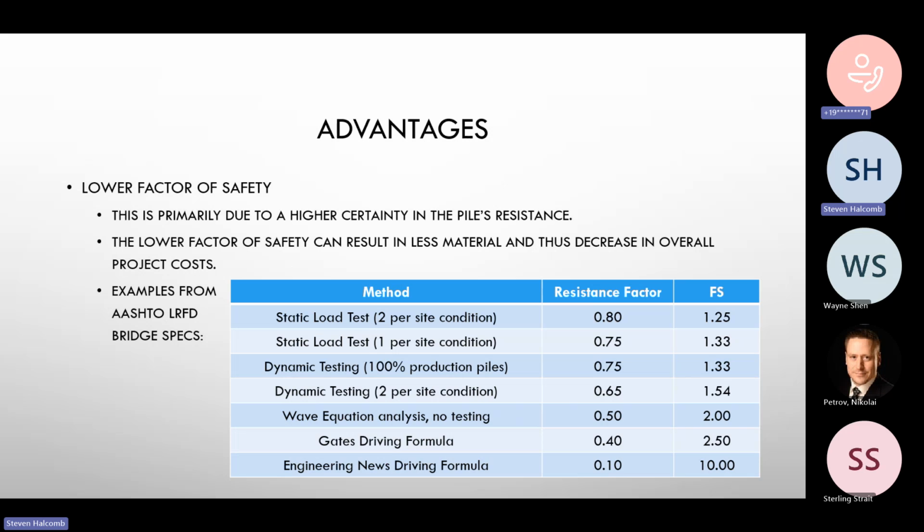So one of the biggest disadvantages is a lower factor of safety. And I really liked what Dave provided from the AASHTO perspective. It gives a bit more comprehension. The IBC doesn't give as much. It talks about it relative to your design stresses, that's the reference in 1810, but it doesn't give you a whole lot more guidance. AASHTO gives you a little bit better. It says, how can I lower my factor of safety based on what I'm willing to do? Because this is a construction verification technique, and allows you to then alter from there.